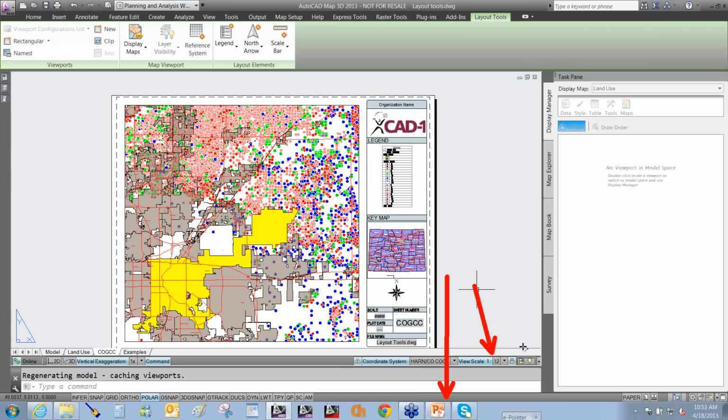You'll notice that once you turn it on and it appears here, I've got the object isolation tools in here. I can turn on my annotation visibility, my auto scales, and, man, I can't tell you how nice that is. It will tell me what coordinate system has been assigned to the drawing, and I can change it right here, but it's always going to be there and in front of me.